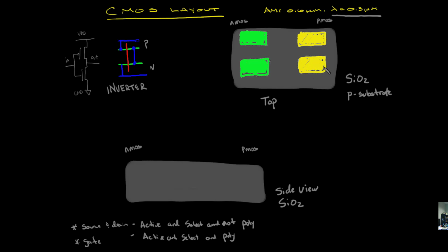And we're going to draw them initially as a box, and we're going to remember that masking property that Virtuoso has when we come back later and fill it with the gate color. When we come back and mask this thing with the gate, that's what's going to separate these two parts. So by simply drawing a box and then putting the poly down, that will create the region of separation between these two and the channel underneath.